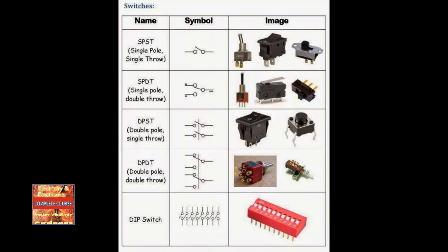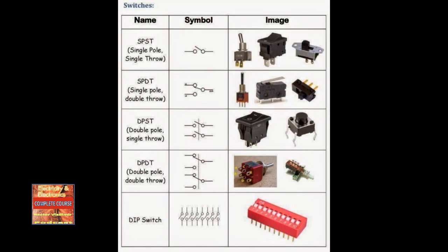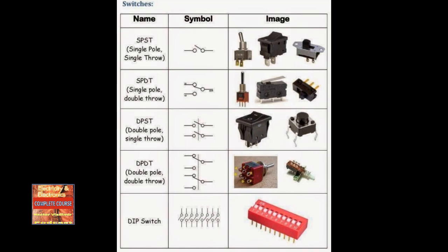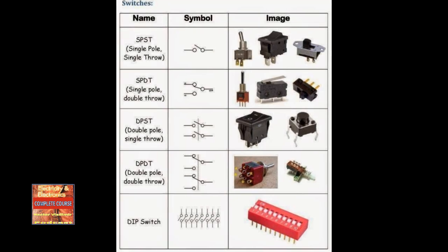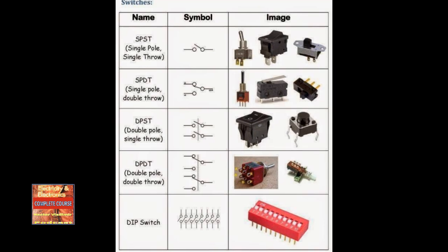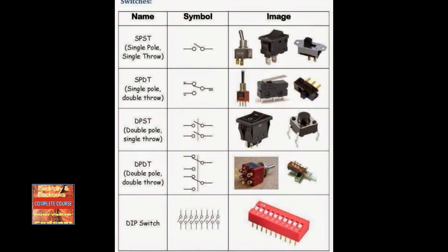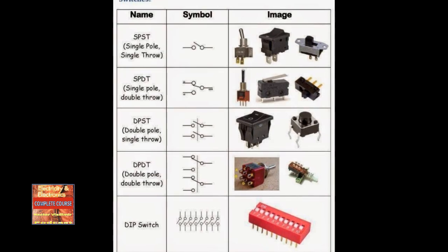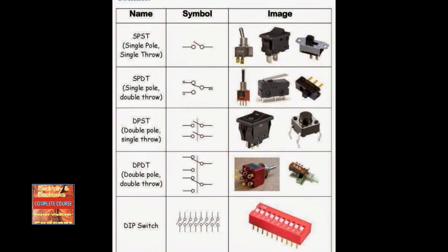In building and troubleshooting circuits, there are some devices that are used in most electronic circuitry. Switches, figure 3.13, are used in circuits to stop and start the current flow in a circuit by the use of a mechanical actuator. This actuator comes in a variety of forms, including slide, toggle, and push button. The name will indicate the type of actuator. The letters SPST stand for single pole, single throw, which means that the switch only has one path for current flow and will only operate one circuit.